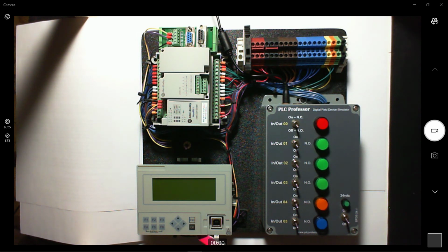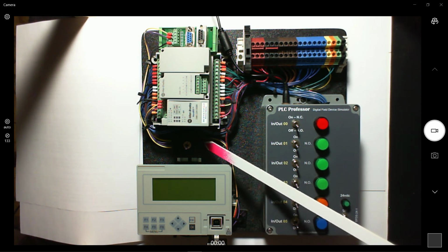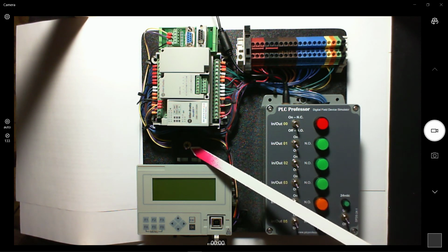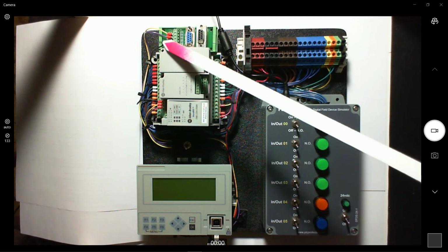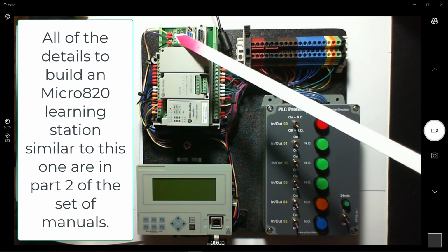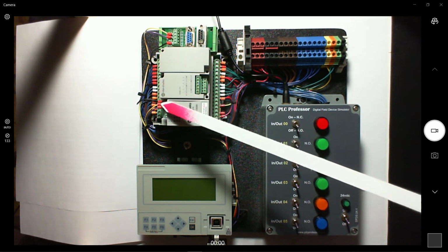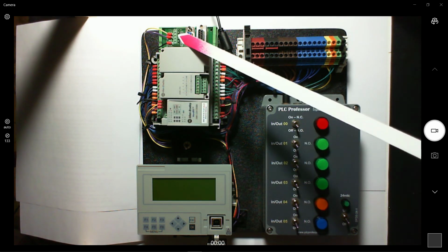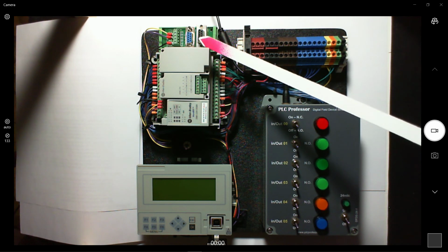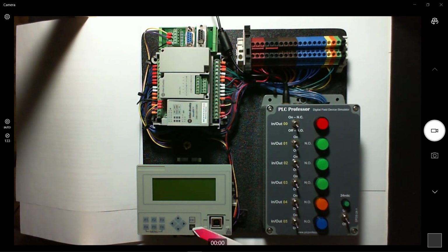Then there's 3 connections over here, and you see all the conductors moving along here. 2 of real interest to us. You've got 24 volts DC, you got 0 volts, which is the black common, but it's the yellow and purple that come over to this toggle switch. Also to this toggle switch, we have connections coming from this DIN rail mount 9-pin sub D shell to terminal block adapter, and you see the yellow and the purple wires. So the yellow and the purple wires come from this RS-232 9-pin sub D shell adapter, and it comes from the 3 terminals down here.